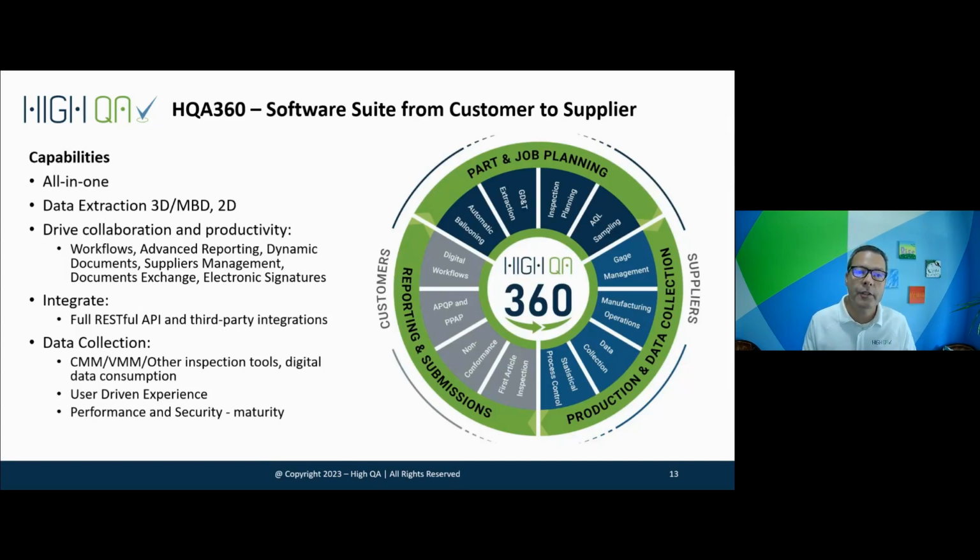But on the production side, you can manage all the gauges in your facility. You can collect all that inspection data for both in-process checks and final inspection. We'll get to that in a little bit. And even provide real-time SPC data, including notifications for out-of-tolerance conditions. And if a dimension's out of spec, it can, if you want, create a non-conformance report digitally.